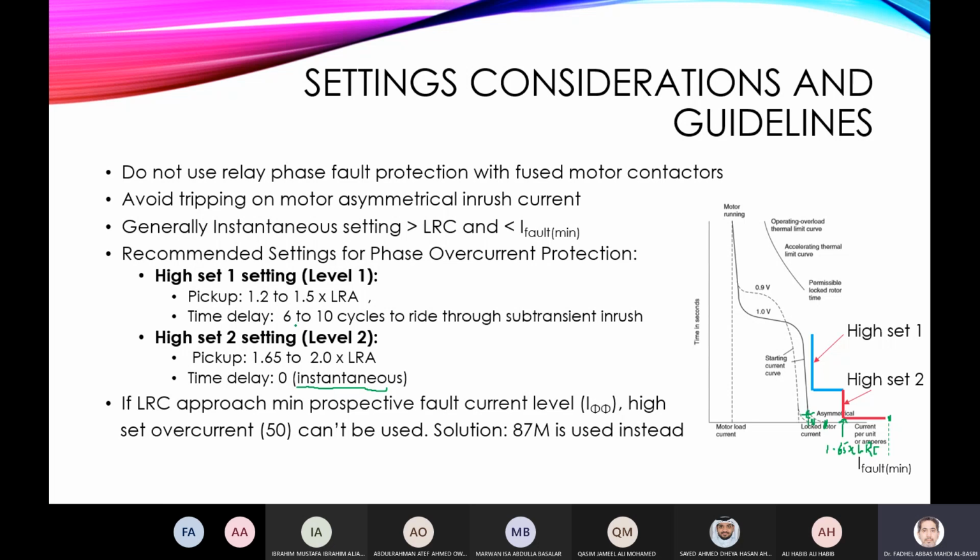Normally this is 6 to 10 cycles, so let's say 10 cycles of 60 hertz, or 10 cycles of 50 hertz. That's about one fifth, so about 0.2 seconds.